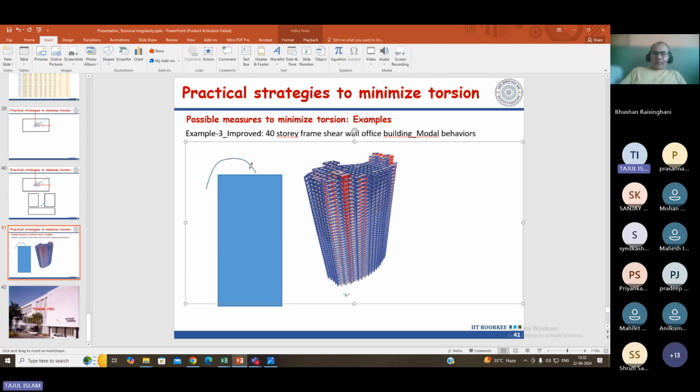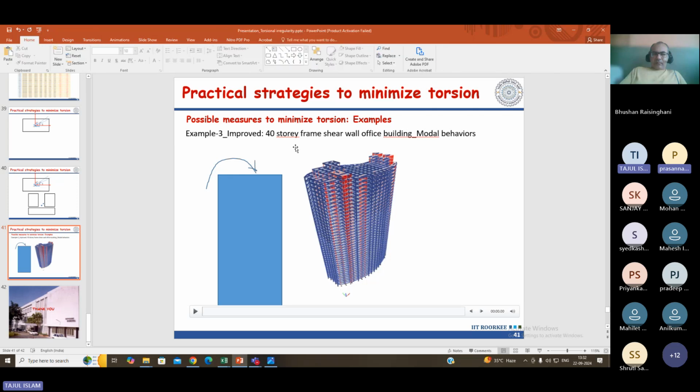This is your moment. Now, this moment can be because of uniaxial forces or because of torsional forces. So what the software does is, whatever force is coming to the structure, it converts these forces into unidirectional force components for each vertical member. The rotational moment acting at the floor mass level will be distributed to each vertical resisting member in terms of movements in the x direction and the y direction.